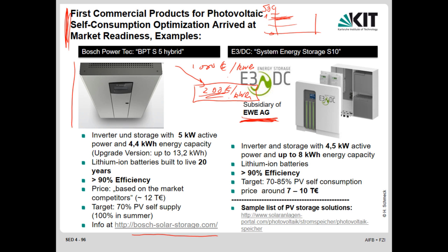Now, if people have batteries, there still is this profile in the background, but what is visible to the company, to the grid, is a completely different profile, maybe very flat, or all of a sudden you get demand for power at a time where before there was no demand, and at times where you had demand before, they are using their own batteries, and so they don't have the demand anymore. It's much harder for them to prepare and to plan for balancing demand and supply in the network. So it's making the job of the distribution system operator much more complex.